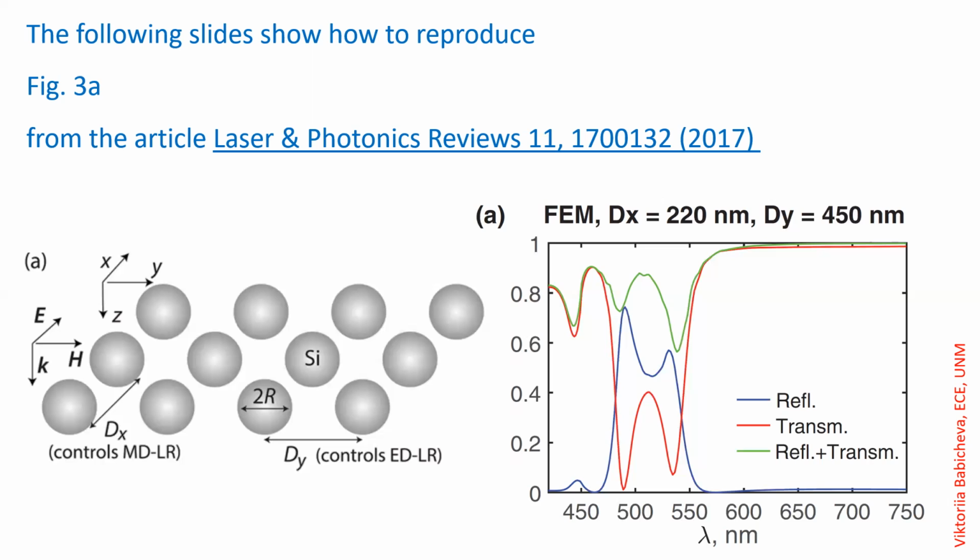Alternatively, we can set up only one homogeneous block around the sphere if the substrate and superstrate material properties are the same and we don't need different mention of those simulation elements. We apply domain mesh, define boundary conditions, and we add excitation source, field monitors, and so on.